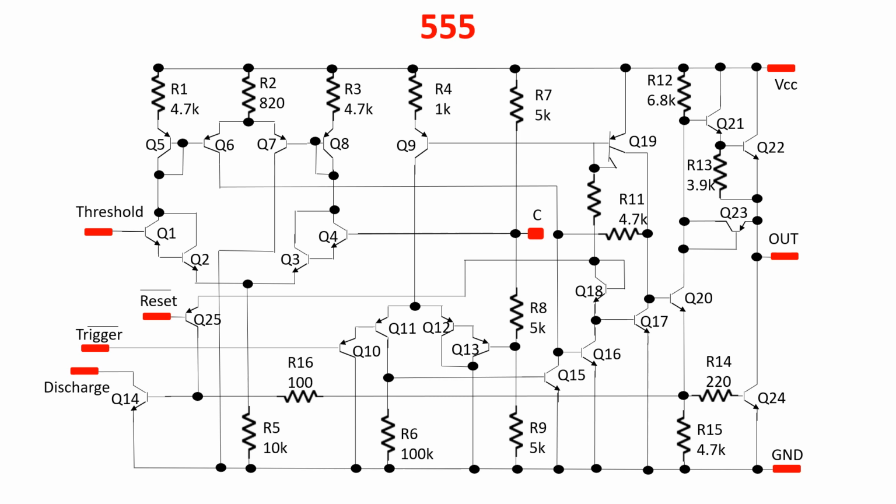The output stage consumes a considerable amount of current in the low state, and during switching both output transistors are on for a brief period of time, producing a current spike in the supply. Despite the fact that much better performance is possible with more modern design techniques, the circuit is still being sold today in its original form.